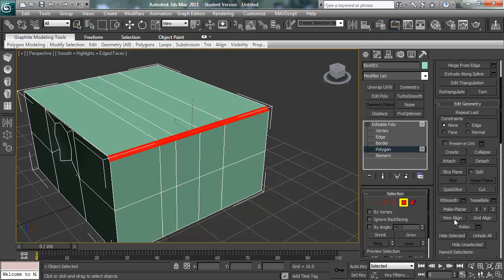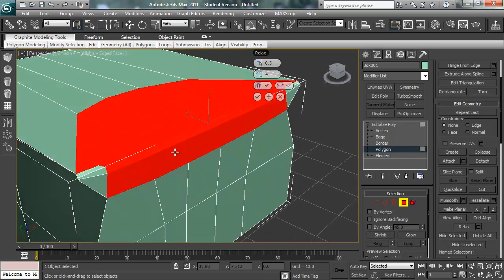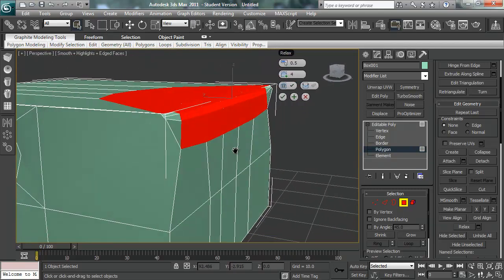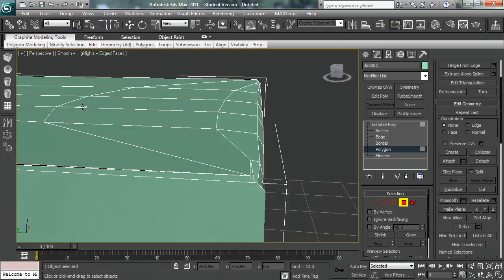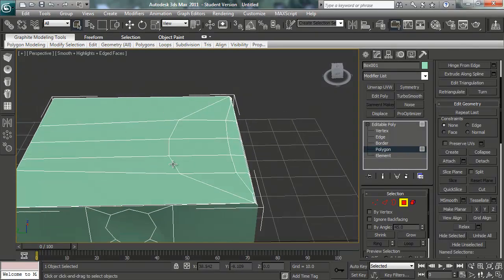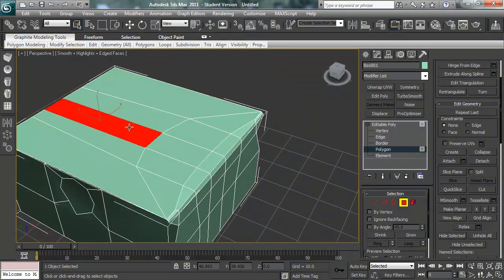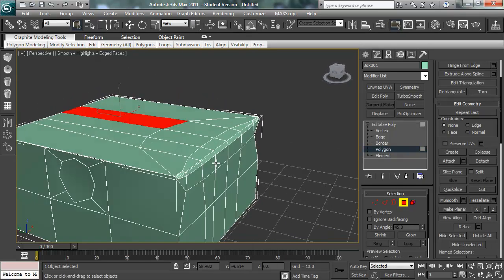Now if we relax it, we'll get kind of unwanted behavior at the sides, but have a look in the middle. You can see that it has made these stretch much further across the geometry to try and get all of the polygons that are nearby to be as square as possible, because these were very long thin rectangles, and it makes it a lot smoother.